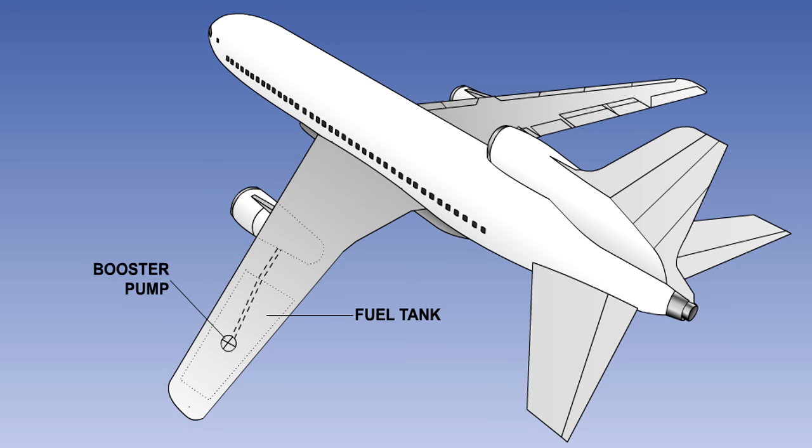Fuel booster pumps fitted inside the tanks can help to overcome this problem by pressurizing the fuel in the pipelines from the tank to the engine, pushing fuel towards the engine rather than engine-driven pumps sucking fuel from the tanks and further reducing the pressure.